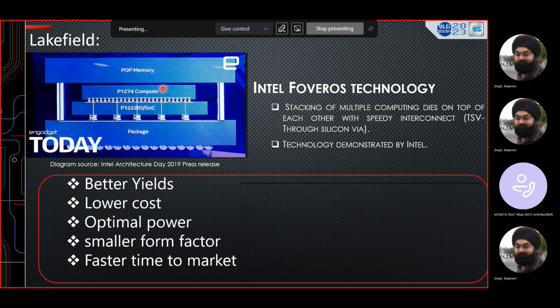And similarly, if you look at the microbump, its inductance is of the order of 10 to 20 picohenry, and coupling components are very small. So that way, it doesn't become a bottleneck for any electrical performance parameter.